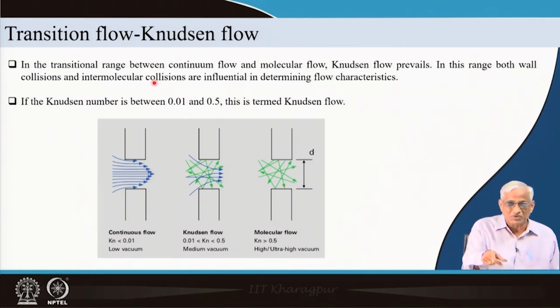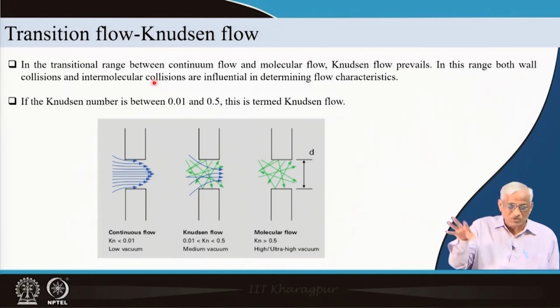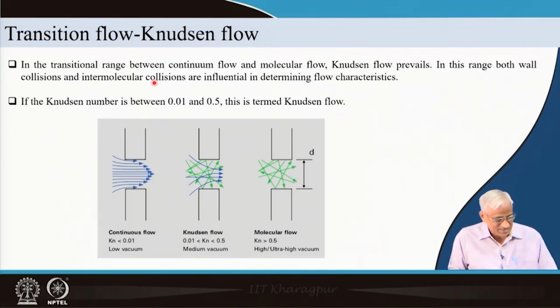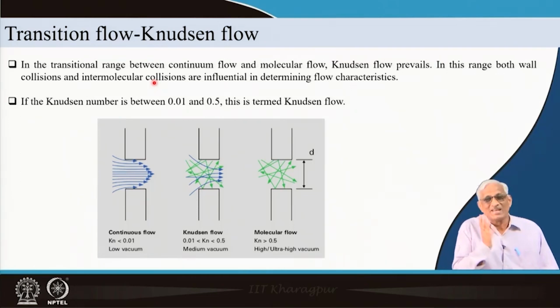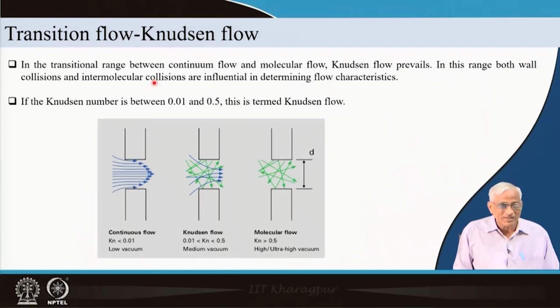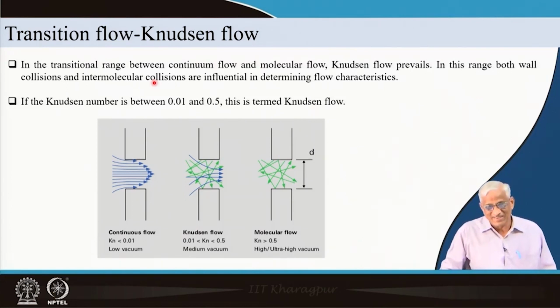When to introduce a booster, when to take out the booster, when to reduce the electrical power, all these things in an overall system design we will calculate for different applications. But keep in mind that molecular flow style is different and laminar flow style is different. And again I am telling you, 99.99% is already removed by the time we cross the laminar flow, but no application has started. That is the beauty of vacuum technology.